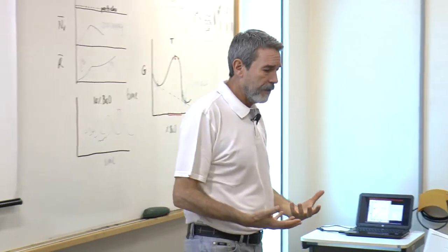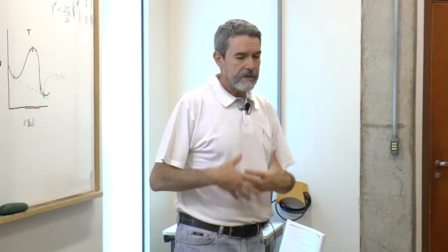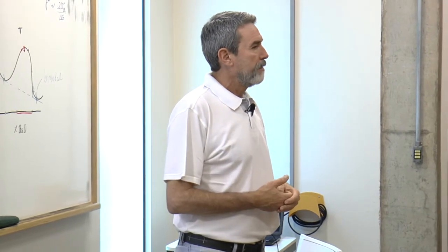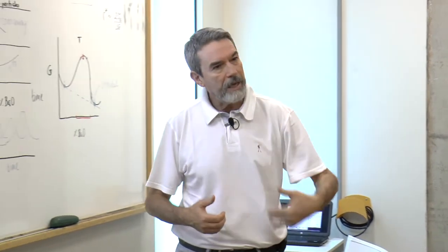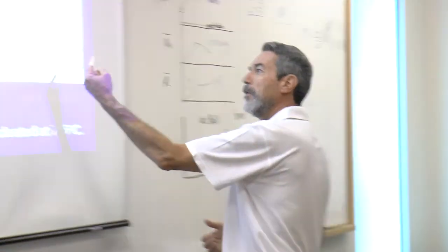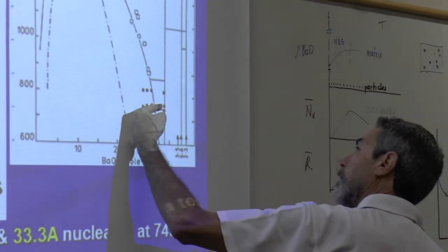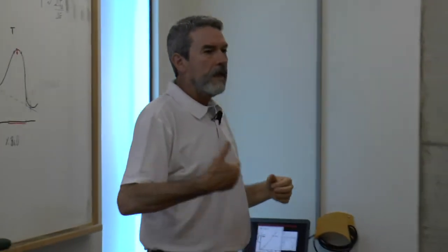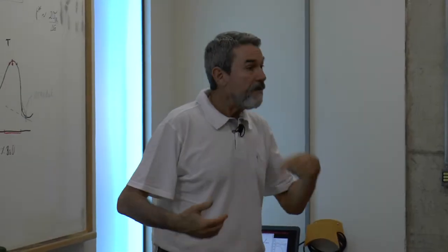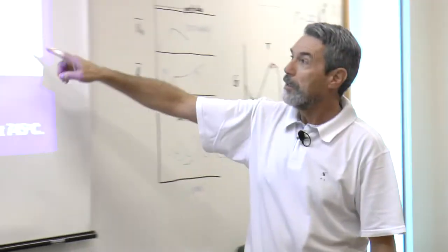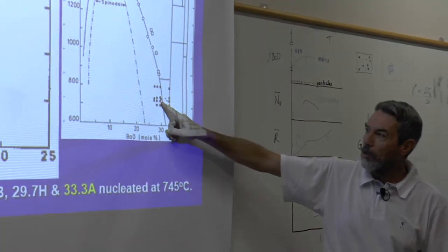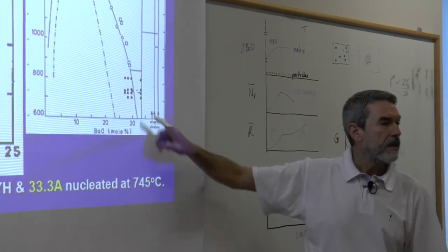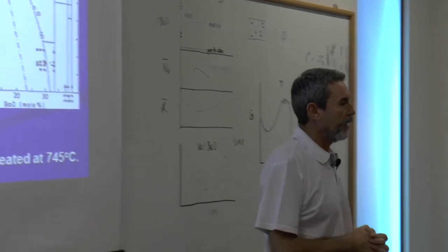We have done many experiments with many other glasses and many temperatures. It's just a compositional effect. The composition of the matrix is becoming richer and richer in barium, so the crystal nucleation rates are increasing, increasing. But they never reach the 33% because the binodal is before 33.3%. This is a purely compositional effect.